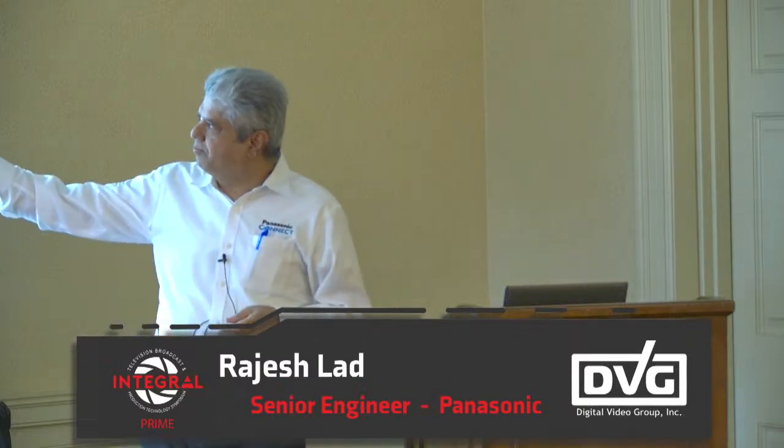And the second part that came in was PoE++ and PoE+. So power over Ethernet became very powerful. It made it easy to transfer video, integrating, just plug in one camera. Everybody uses security cameras at home, just plug in one Cat5 cable, it gets power over Ethernet, and you have a stream coming out of it, and you can watch it on a phone or something.